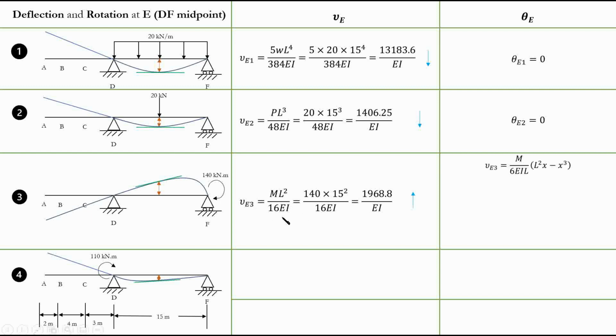However, in terms of rotation, you cannot really find any value directly for rotation from your tables, right? So we are interested in this point. However, in your table, you don't have the theta value, right? So now this is when we need our general equation for deflection. Now, very important concept. Our rotation is basically the first derivative of our deflection curve or elastic curve. Why? So what is this equation? This equation is the equation for this curve, right? It is the equation for this curve.